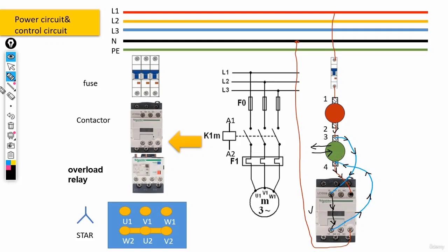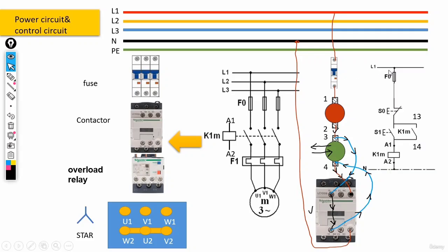Alright, now let's take a look at the wiring diagram or the electrical symbols that we have for such a circuit. As you can see, we have the contacts here, 13 and 14, talking about these two. And they are connected to the contacts 3 and 4 in our start push button. And somehow created an alternative path for our electrical current. And well, as I said, this would turn on the contactor, but this time it would be permanent. Alright. By the way, guys, these types of control circuits, let me mark it out.